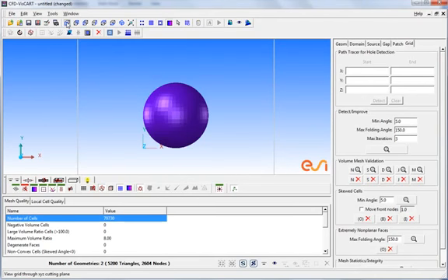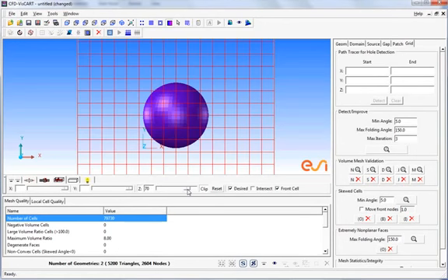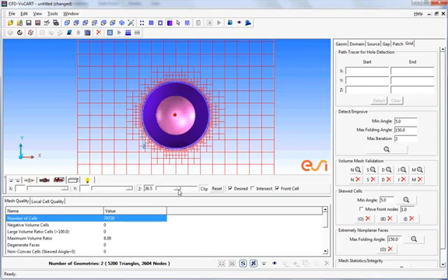To verify that the domain marker lies within the inner sphere, we can use the clip option with the cut plane. The clip option clips the part of the model that lies in front of the cut plane, allowing better visualization of what lies inside. We can see now that the domain marker is inside the inner sphere. The mesh still appears outside as the previously generated mesh has not been deleted.